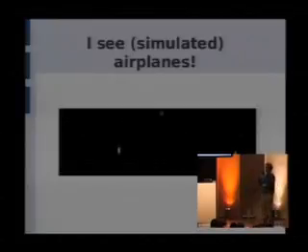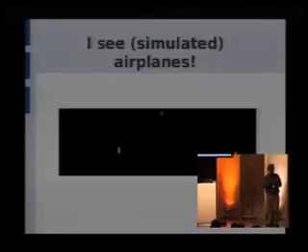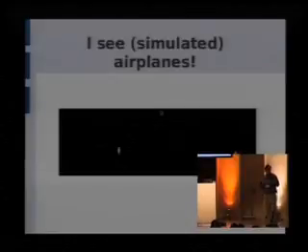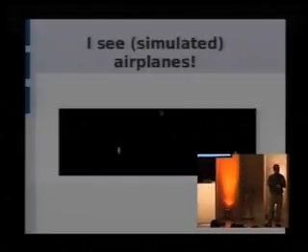If you start thinking about how, let me back up for just a second. Remember I was talking at the very beginning of the talk about how they had these radar systems where they sent out a pulse and then they stop transmitting and then they listen? Well, we don't control the transmitter, so it's on all the time. So the trick we get is that we can listen for a long time. And it turns out that the broadcast FM signal, particularly if it's tuned to something like very raucous rock and roll, has really good properties for us. If they're just talking, it's not so good, seriously.